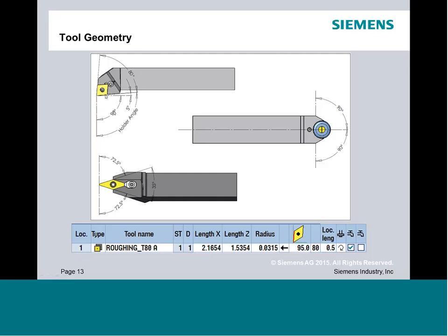Now for us, this is going to be entered in as what we call the holder angle. The holder angle is the total distance from 0, or from this base plane, all the way to the relief angle. The holder angle can be seen right down in the lower description where we have a value of 95. So when inputting a value and getting the correct orientation of a tool, you want to use whatever they call out the relief angle to be, plus, in this case, 90 degrees.